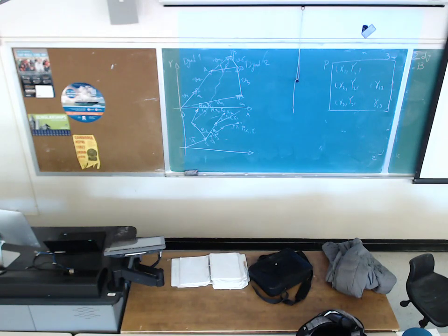Then the mechanism is rotating from the first precision point to the second precision point. This line should rotate by the angle of gamma 1, 2. So if you draw a line parallel to this, the angle between these two should be gamma 1, 2. And point P should move from these coordinates to these coordinates. And if you connect, this angle is going to be theta 1, 2.